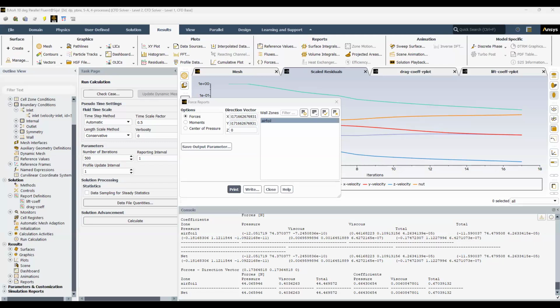Now the same angle will be made with the lift part with the y-axis. Okay, so 10 degrees. And you know from very basic trigonometry, where the angle is there, you have to put the cos component there. So y will contain the cos of 10 and x will contain the sine of 10. And you know that when the angle is negative, cos will give you the same value, no sign change.